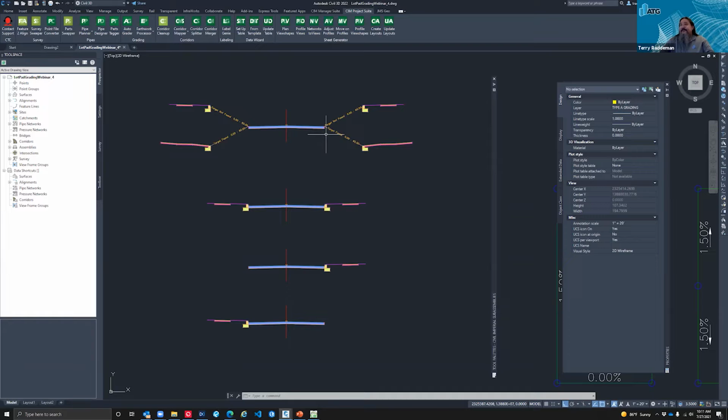The benefit of conditional targeting is so we're not cutting up our corridor into many regions. We can develop an assembly with a curb and a driveway and a sidewalk, and we can chop up our regions and assign a different subassembly to that section. But using conditional statements, we can reduce the number of assemblies that we have, and also the number of regions that we create through our model.